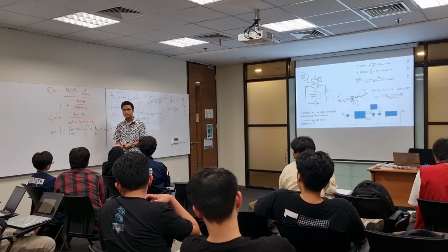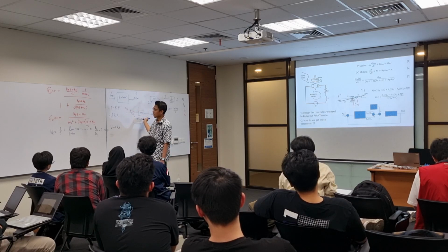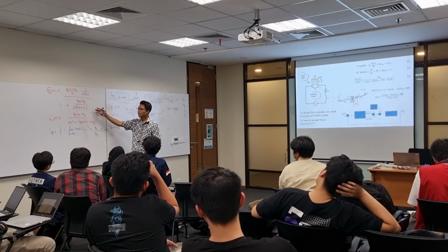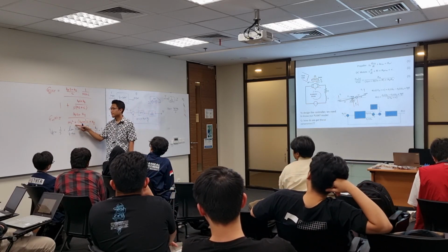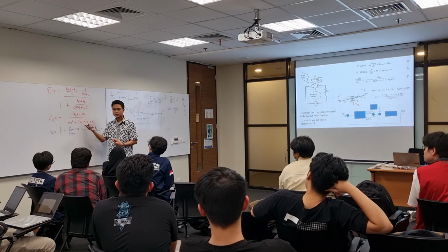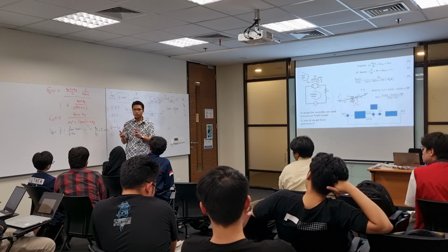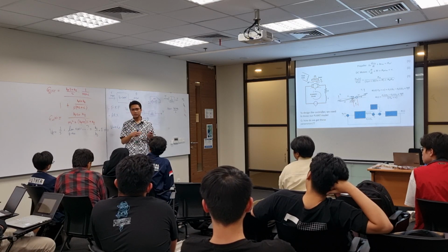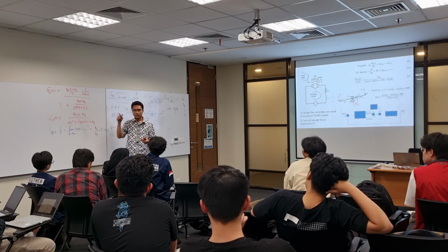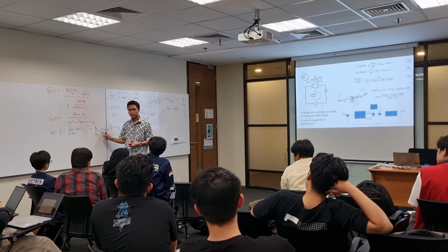Do you realize it now? Even if your mass is not exact, you can still get the final value to be 1. However, the real mass and your chosen controller are going to affect the transient response. That's correct. So when you work as a control system engineer, you have to do fine-tuning to get the desirable transient response. But this final value is guaranteed.